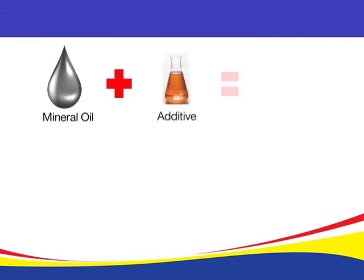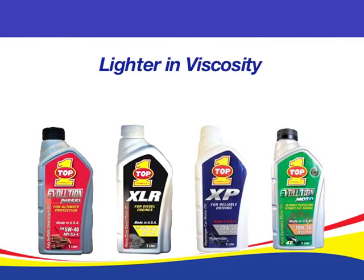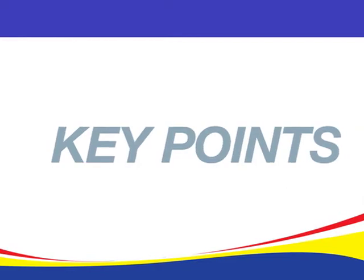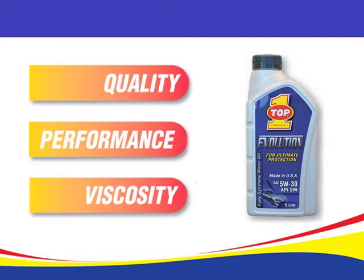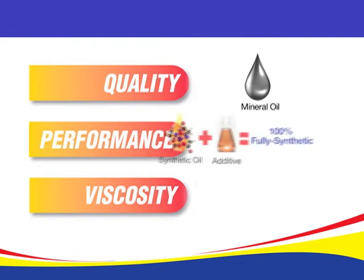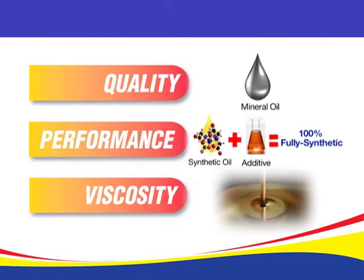With the robust additive packages that are available today, motor lubricants can be lighter in viscosity and yet still provide excellent protection. Here are some key points to remember. There are three major characteristics of an oil: quality, performance, and viscosity. Quality comes from the base oil, performance comes from the additives, and the viscosity defines the thickness of the oil.